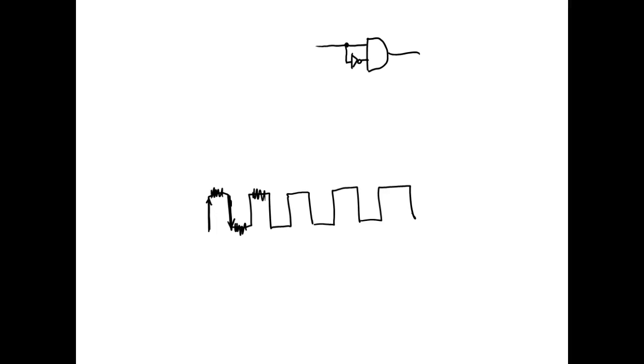There'd be no way in the world we'd get all highs. So this is why one of the things we said: A AND with a 0 would always give us a what? A 0. But that's not exactly true. That's ideal. But the problem is, when we do that, we're ignoring the propagation delay of that chip right there.